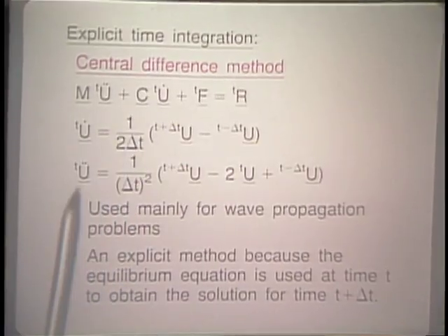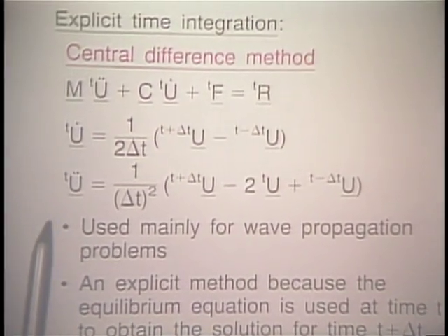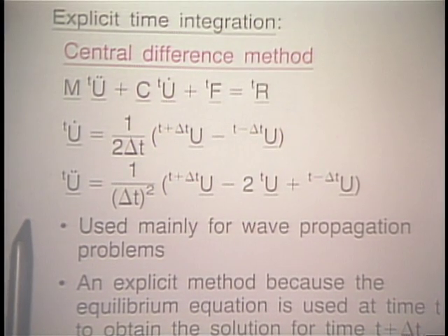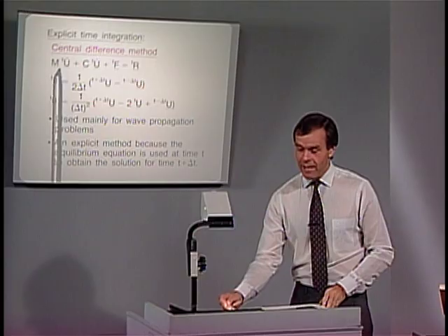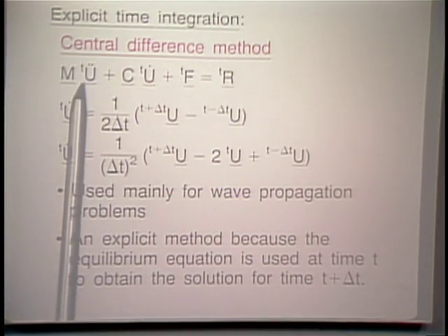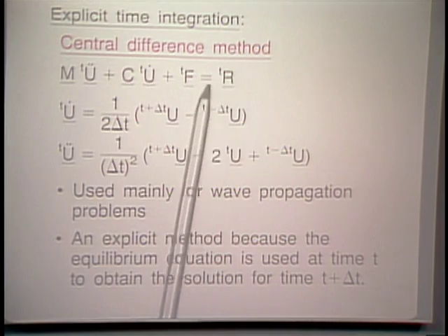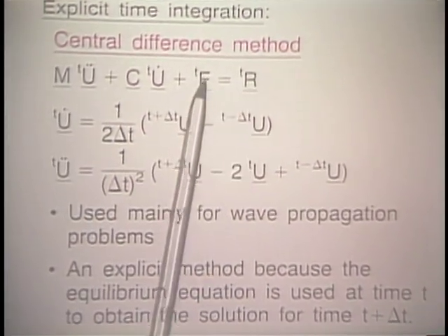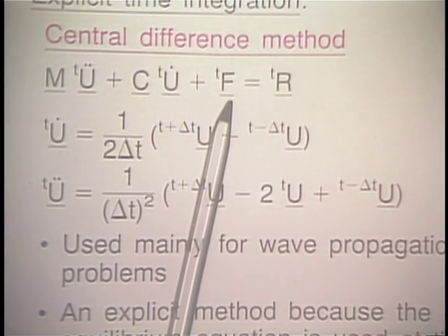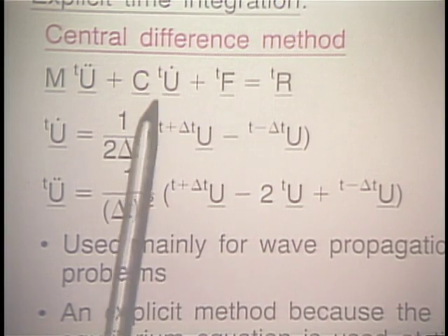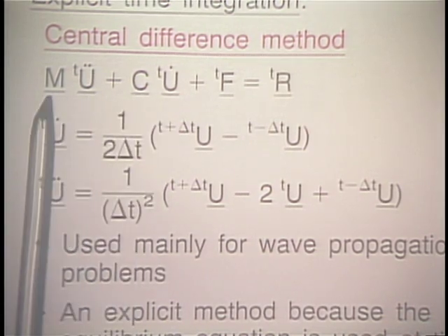Let's talk first about the explicit time integration techniques. And the one that I like to focus attention on is the central difference method. The central difference method is very widely used to solve nonlinear problems. It's an explicit technique, as we will just now see. The basic equations that we are working with are listed here. This is the equilibrium equation at time t. Notice here is the tF, the force that corresponds to the internal element stresses at time t. Here are the damping forces, and here are the inertia forces.